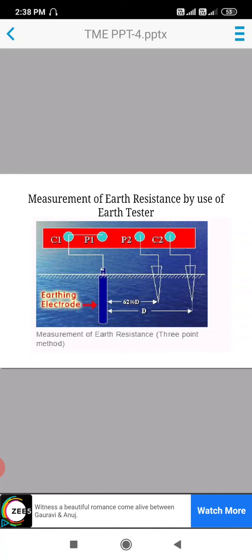These three electrodes are connected to the earth tester having 4 terminals: C1, P1, P2, C2. C1 and P1 are short circuited with the help of a wire, and connected to the earth electrode. Then the current electrode is connected to C2 and the potential electrode is connected to P2.